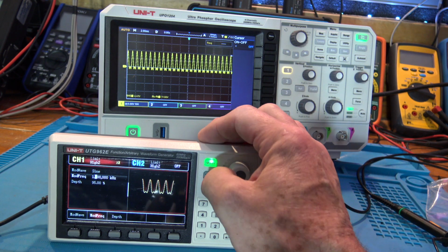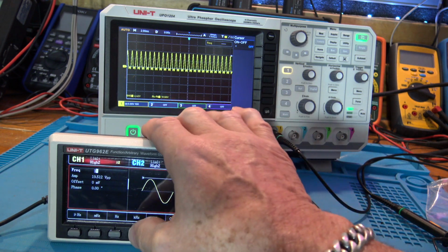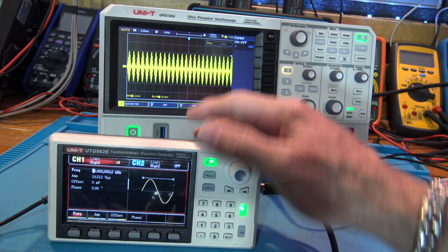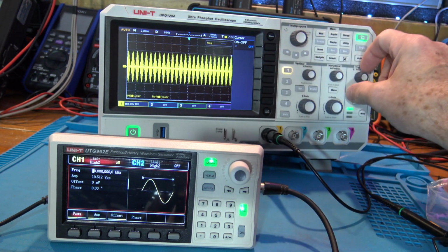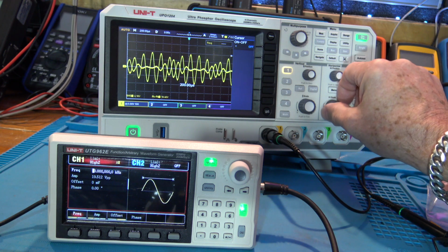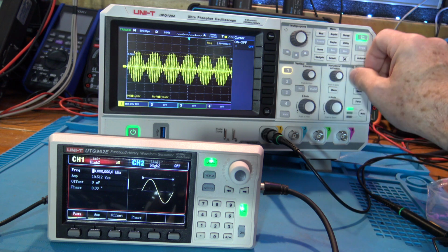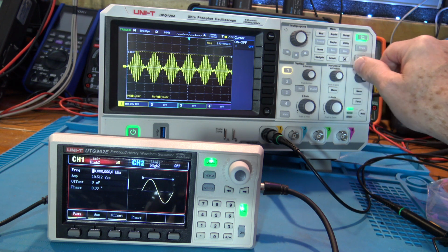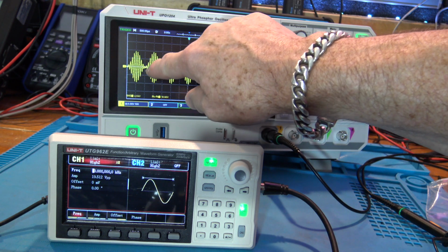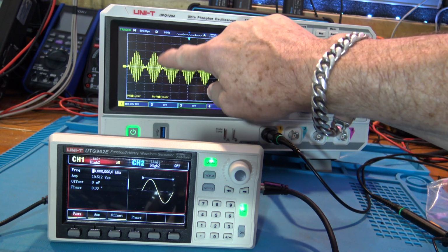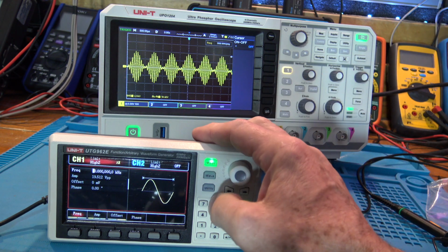So if I go back to my sine wave, and go to frequency and enter 10K, like that. Now it's a 10 kilohertz sine wave, high frequency, but it's modulated at 1 kilohertz. Bring the trigger right down there so you can see it. Okay, so 10K, and we should have about 10 bursts in between every 1 kilohertz. So yeah, that's the modulation.